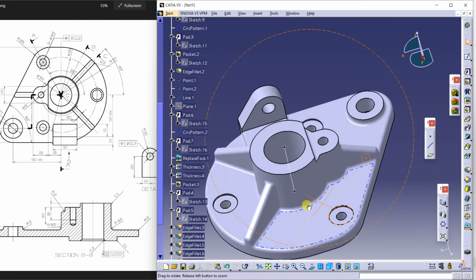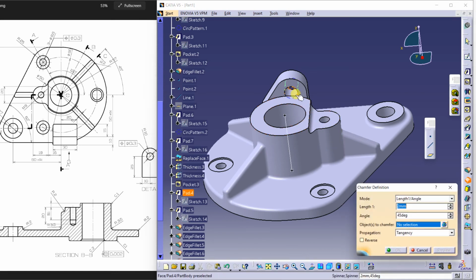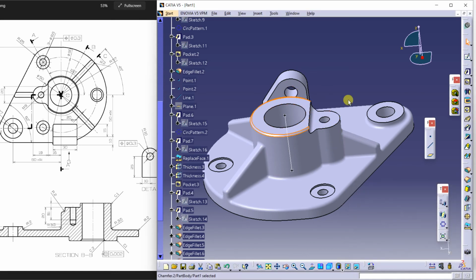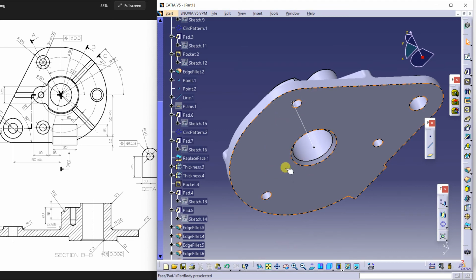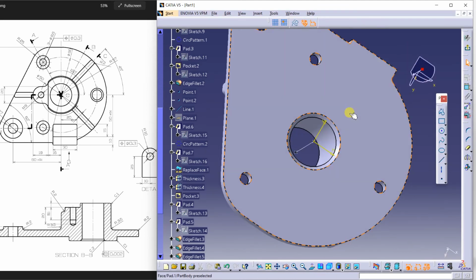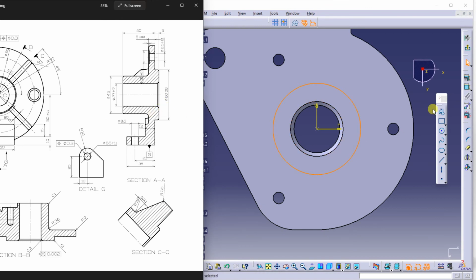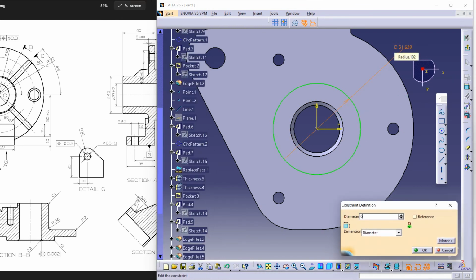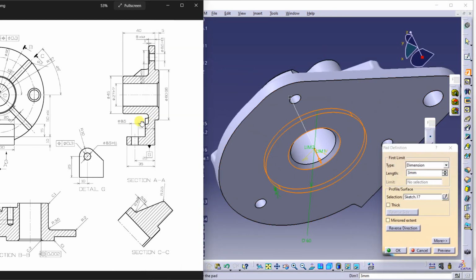So this is our model, and we have still something. This chamfer is at this portion, which is 1, okay, and 2, 2, 2, 2. We have already defined chamfer inside and outside. Okay, something we have missed here. Okay, so click here and here. Here we have a circle. Draw a circle, and this circle is 60 diameter. Define it 60 and finish it. Extrude it, and the thickness is